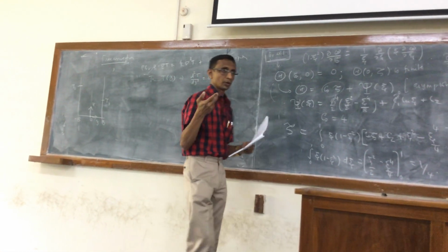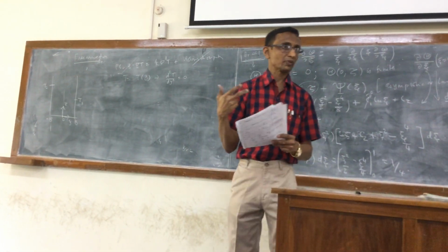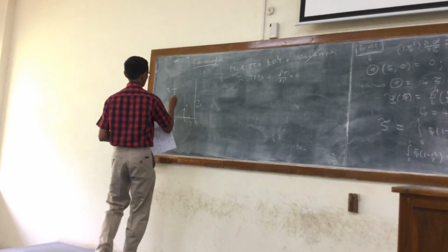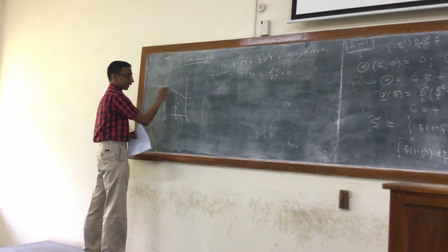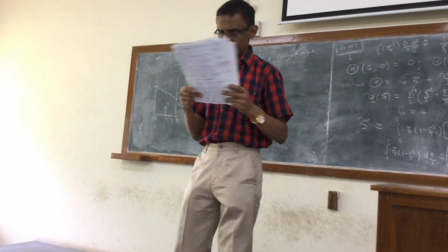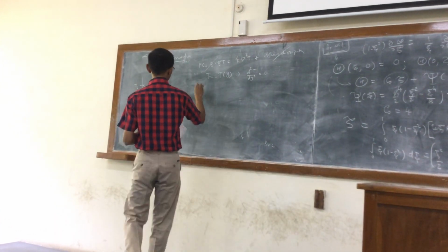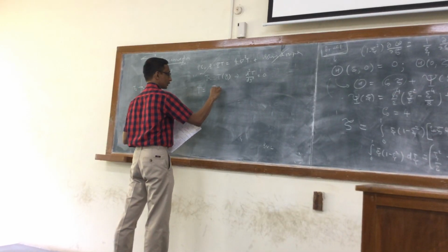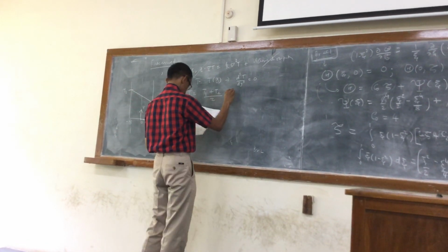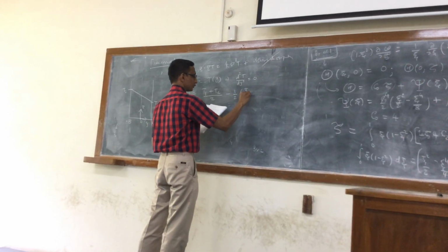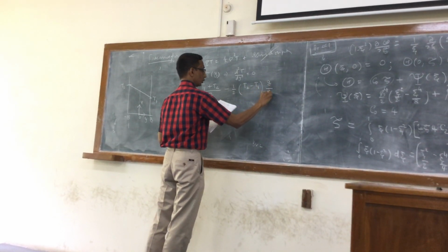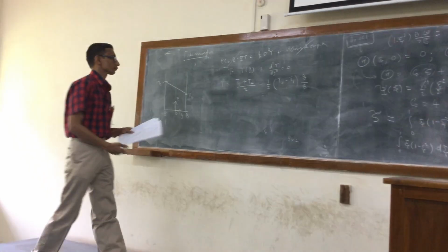We know the well-known linear profile, as in heat conduction in a solid. Actually, this is only an approximation. If this wall is hotter than this one, then the temperature profile is going to look like this, and he writes the temperature profile as T1 plus T2 over 2 minus half times (T2 minus T1) times y over b.